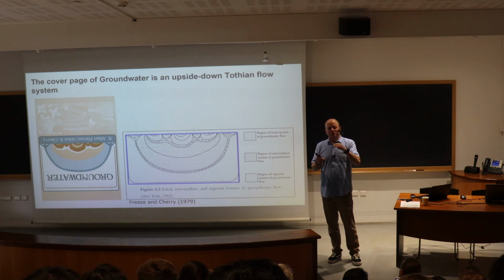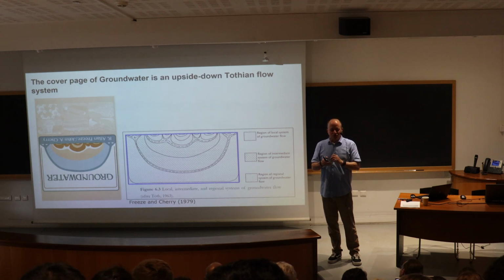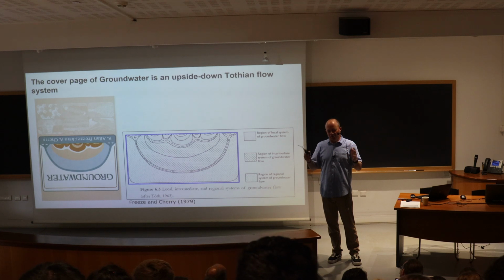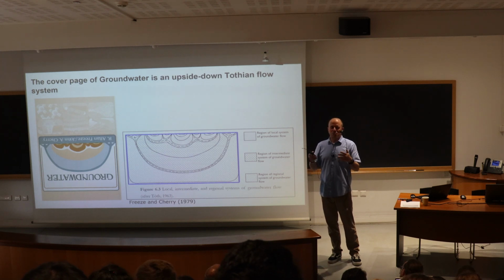And of course, if you're simulating, I say we do a lot of catchment scale. Well, we have the atmospheric boundary conditions. So rainfall, snowfall, snow melt, and so on. I'd say the top surface is not so, I won't say it's not so difficult. You still have to make choices, but as soon as you do some subsurface modeling, it's not a guess, but you have to use your best judgment, and ideally then you would have to change the boundary condition.